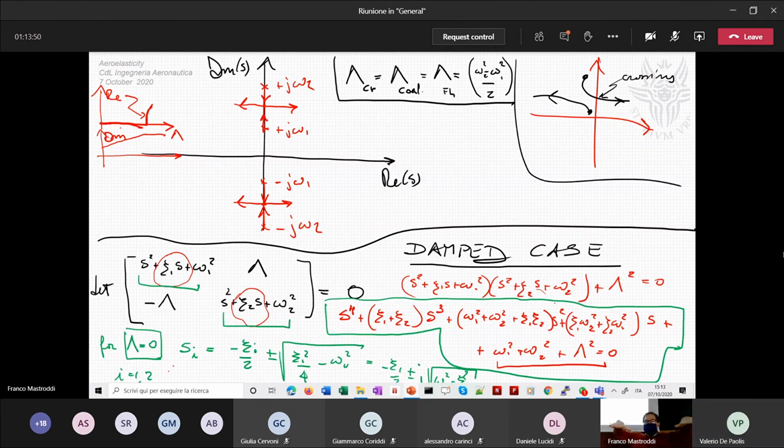And you have a couple of modes, in the sense of aeroelastic modes. After the critical value, you have this pole and this pole. This pole is stable, but this is unstable. And this unstable value will give you an oscillating diverging solution. Clearly, and this is the expectation by linear theory, period.